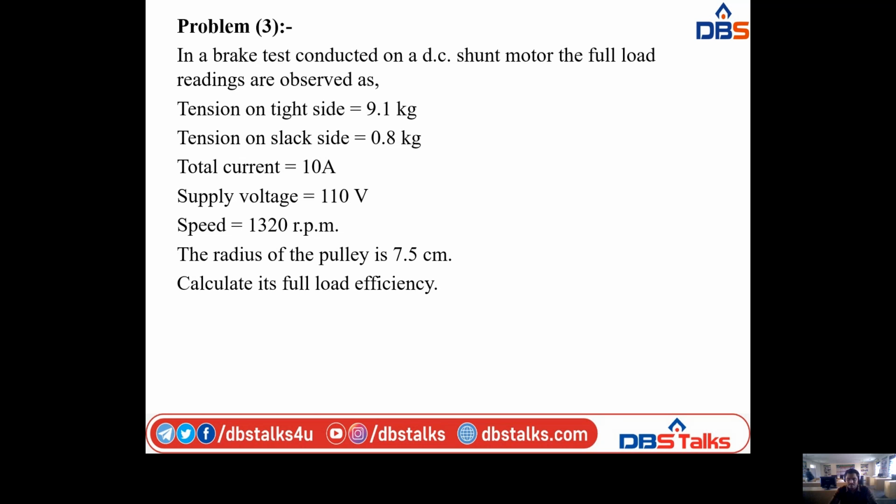They have already given the average current, 10 amperes, and we have to calculate the average voltage across the load. In the data, the induced voltage falls from 240 to 220 in 25 seconds, so the average voltage across the load is (240 plus 220) by 2, and finally we have 230 volts.